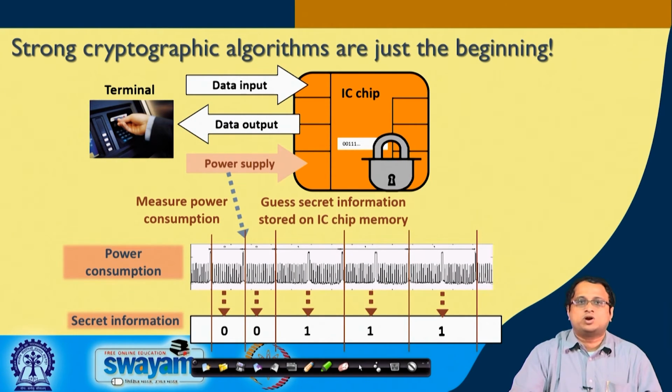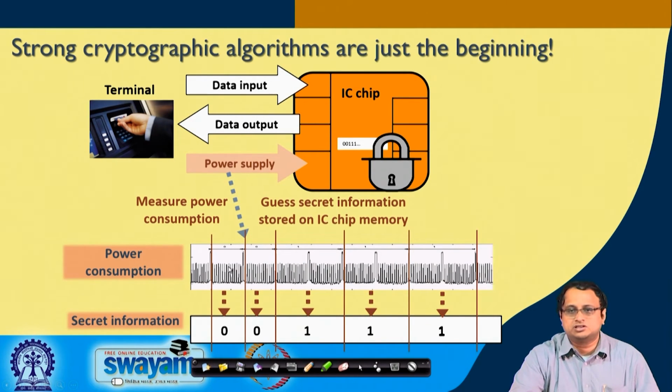What may happen is that from the power consumption, depending upon the glitches on the power rail, you can probably infer that the secret key bit was 0. And if the glitch is larger, then you see that it is probably doing an additional step, and the additional step is probably a multiplication. Therefore it will give you the secret key in order n amount of time, a linear amount of time. So you are not really challenging the mathematics behind RSA, but you have a very easy way of getting the key, because your target is mainly the implementation.